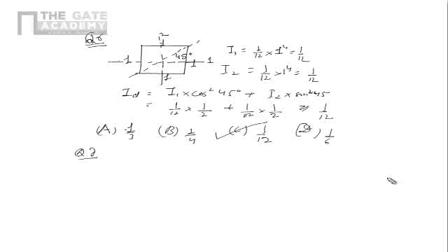Now let's see question number 7. Question 7: a lean elastic beam of given flexural rigidity EI is loaded by a single force F as shown in the figure. So this is the elastic beam. Now there is a support. It's like an overhanging propped cantilever, and there is a force F acting on the free end. How many boundary conditions are necessary to determine the deflected center line of the beam? Now that's a good question.